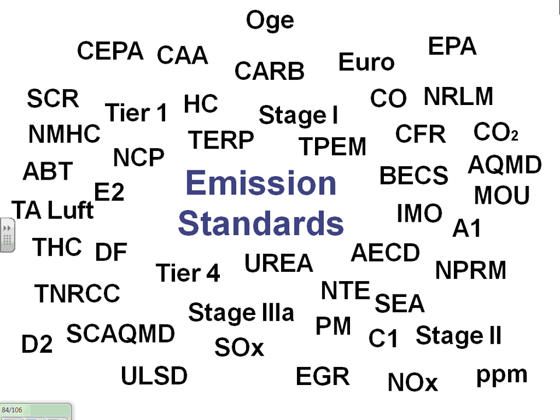One of the primary things for new engines that we're dealing with today is we're going to a Tier 4 engine by the year 2015. What that means is we've been in progress so far. A lot of engines are at Tier 3 now. We do have some that are at Tier 4 already, but they're little engines. They're cleaning up the exhaust. Primarily, the concern that you see is this guy right down here in the bottom, NOx. And the way we clean that up is with what we call an SCR.